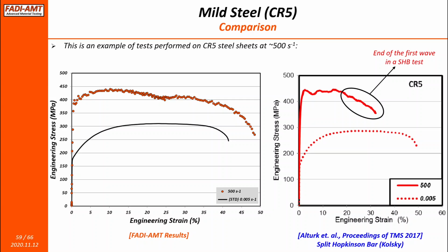You can see our curve is not the quality of the other curves that we obtain for other materials. And that is a problem with certain materials. Mild steel, this sample was very soft, very thin. This is a 0.6 or 0.7 millimeter thick sheet. So we have a lack of stiffness here. So we tried to eliminate ringing there, but you can see a big dip in the middle of the curve that we couldn't eliminate.